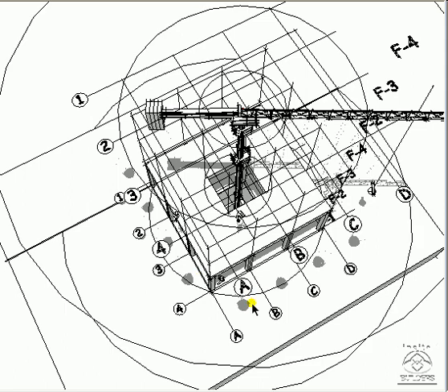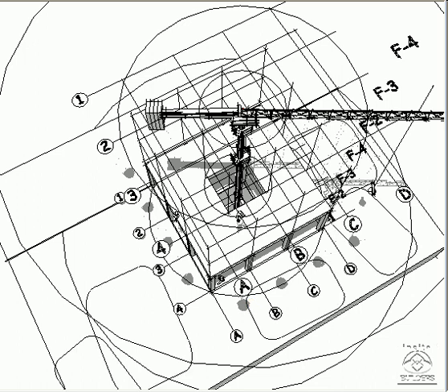In addition, the arc of crane movement can be mapped over the grid with compass points. The arc also references the distance along the boom for pickup and placement in staging and assembly areas. These areas are designated pickup points or shakeout areas, control zones, and assembly areas. Like a crane operator, you can set control markers to return to these spots over and over again.